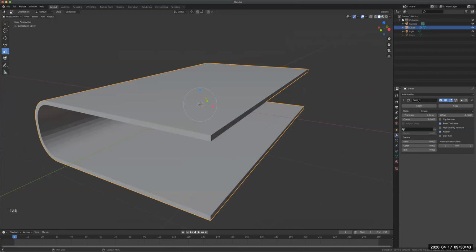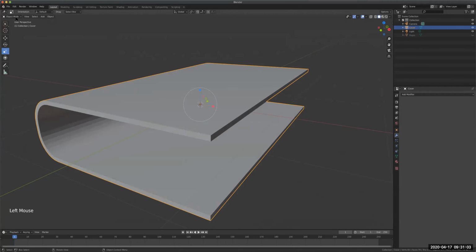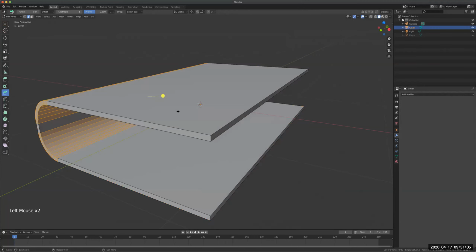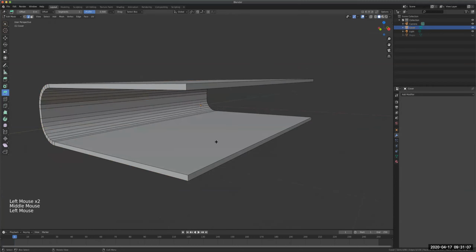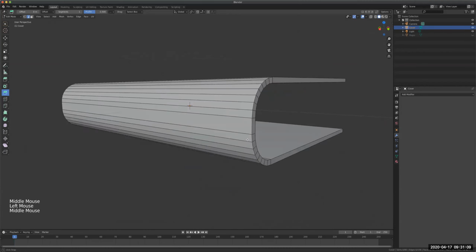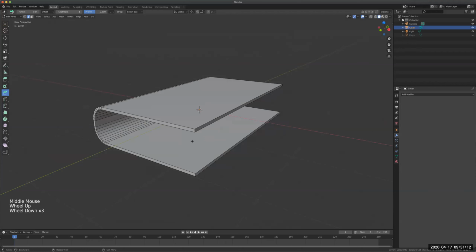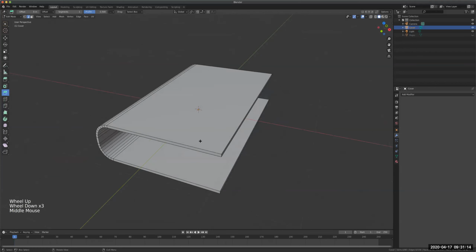So once you apply a solidify or any modifier to an object, it becomes a permanent part of it and it goes away from here. So any parameters that you want to change, you have to do that way before you hit apply, because you won't have access to it, okay? I'm gonna hit apply. What happens? It disappears. When I press tab or go to edit mode, we now have access to the solidify thickness as if it's part of this, okay? So now it's a solid mesh ready to go, okay?